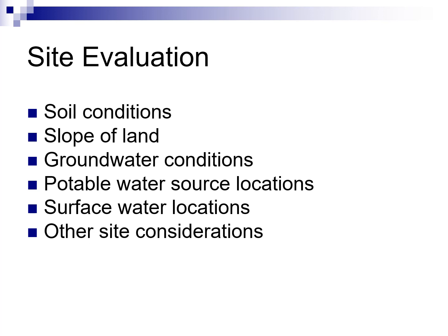The first thing I look at is the soil conditions, right? I'm going to run a test, which I'll explain in a few minutes, called a percolation test, so that I could see how much the water drains into the ground. Also, I have to look at the slope of the land again, because water tends to flow downhill. I also want to look at the groundwater conditions. So if groundwater is right below ground, then I really can't add my septic to it because it won't go.